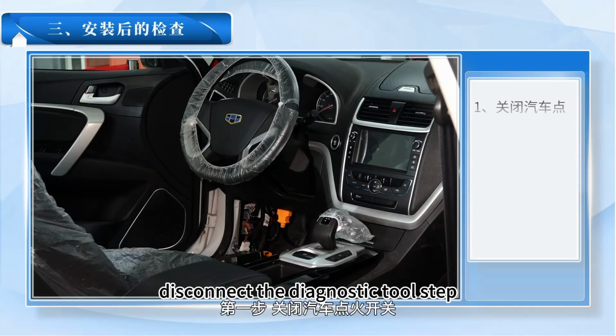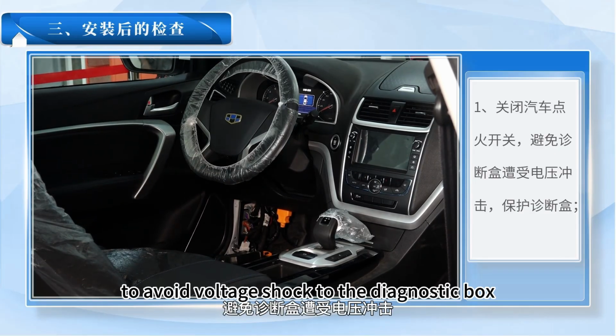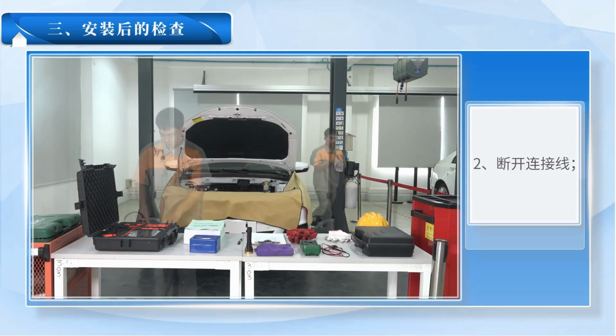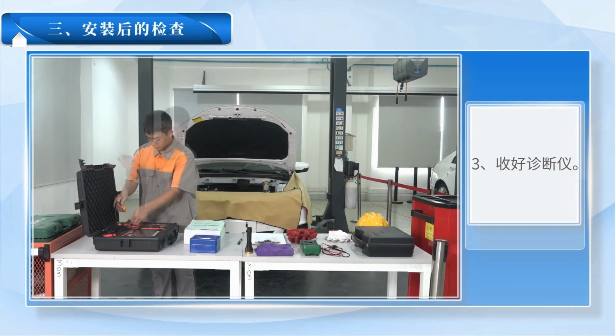Disconnect the diagnostic tool. Turn off the car ignition switch to avoid voltage shock to the diagnostic box. Protect the diagnostic box. Disconnect the cable. The third step is to put away the diagnostic tool.